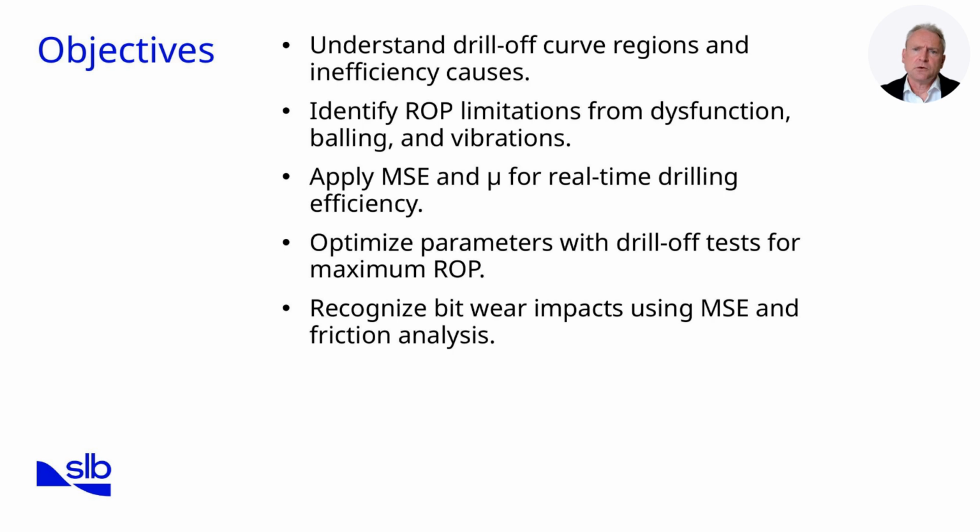Third, we'll apply 2 important concepts, mechanical specific energy and the bit friction coefficient, to evaluate drilling efficiency in real time. Fourth, we'll examine how drill-off tests can be used to optimize weight on bit and rotary speed for maximum rate of penetration. Finally, we'll see how to recognize bit wear impacts using MSE trends and friction analysis, which provide a powerful way to detect declining bit condition before it becomes critical. With these objectives in mind, let's move into the technical content, starting with on-bottom ROP enhancement.